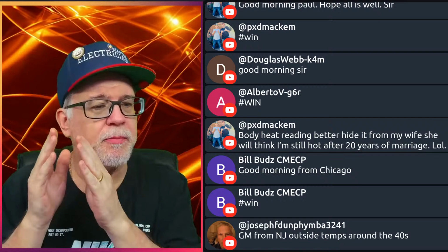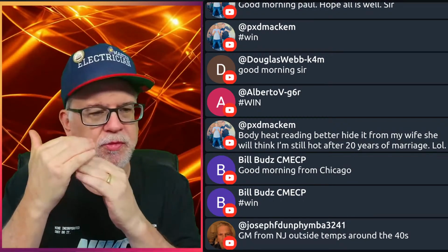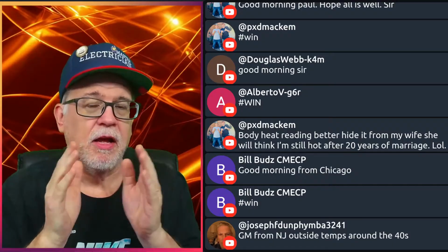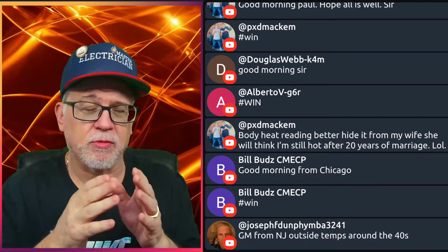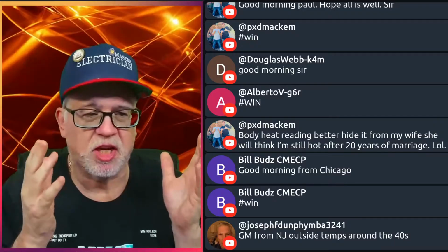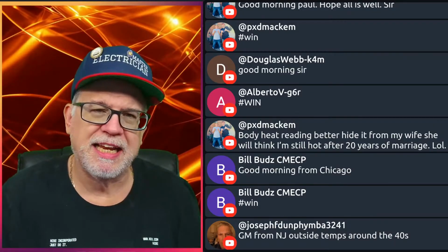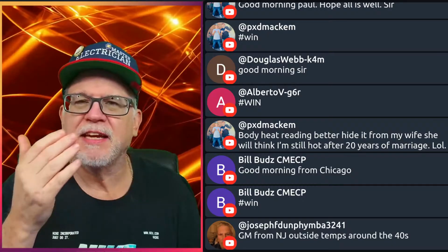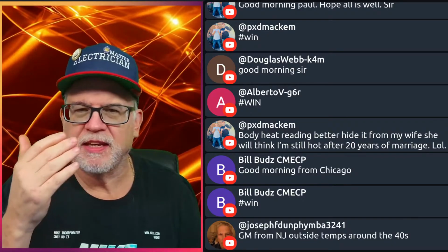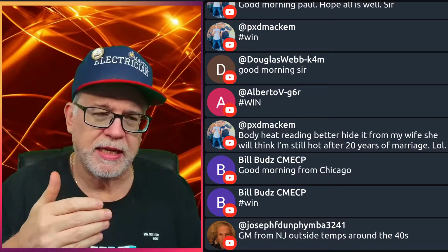Whereas I look at the other mutual conductors on that breaker, let's say, and they don't have the same temperature difference. And it means that now, it doesn't mean it's imminent failure because we want to record that. And sometimes you see this bright color and you think, oh my God, it's going to fail, only to look at the temperature and realize that it's nowhere near a temperature that would exceed the insulation of the conductor or the overcurrent device. And it's under normal loading.